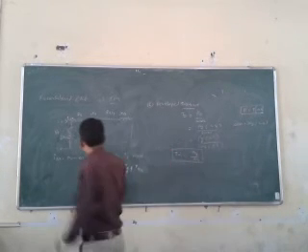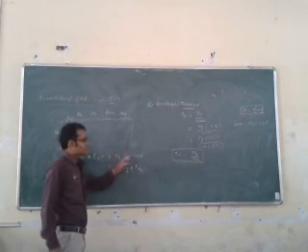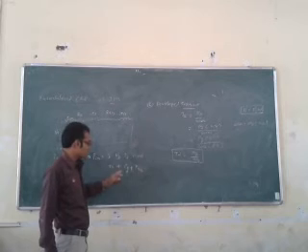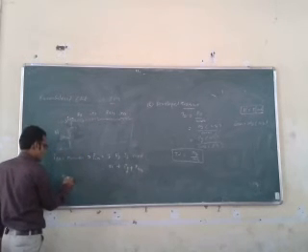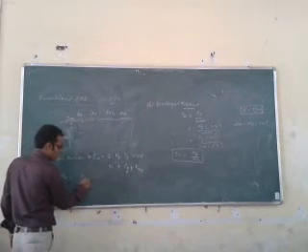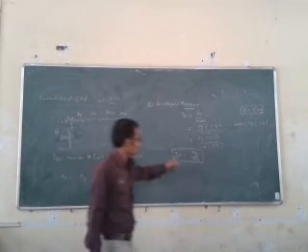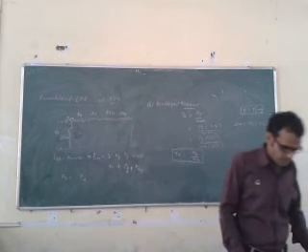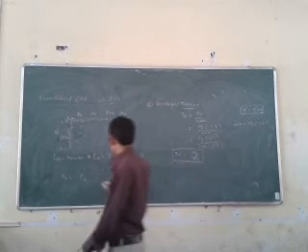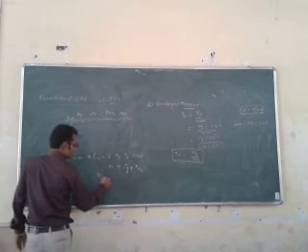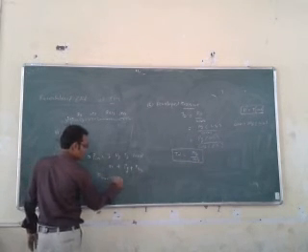This is the input. Input is equal to 3 times VS IS into cos theta, which equals PC plus PG plus PS. Similarly, what is the output power? The final output power, what we discussed, that developed power, right? Power developed minus no load losses.